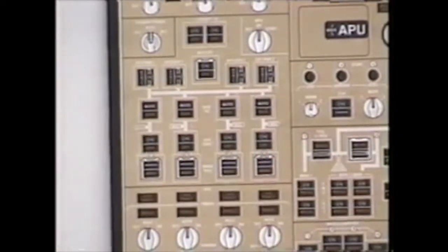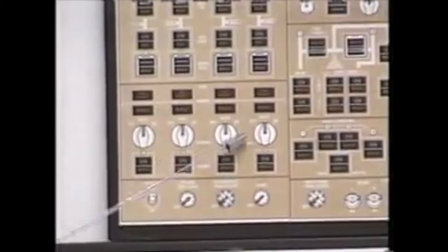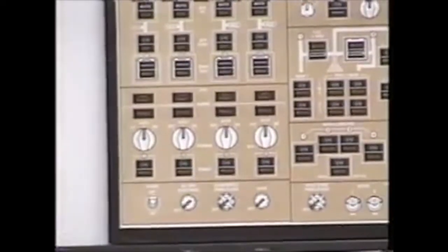The ground handling bus provides power to such items as the cargo loading, to include the doors, the lights, the rollers, fueling, except for your stabilizer, and the aux hydraulic pump in System 4.